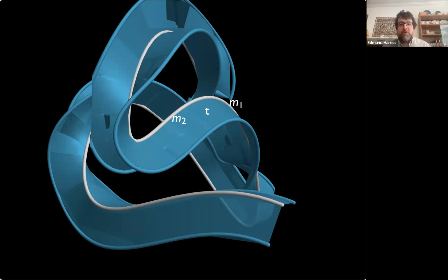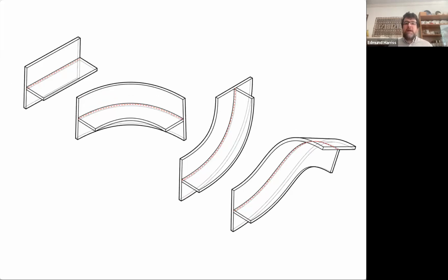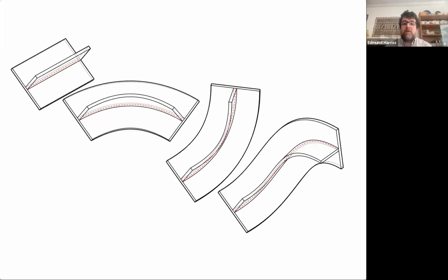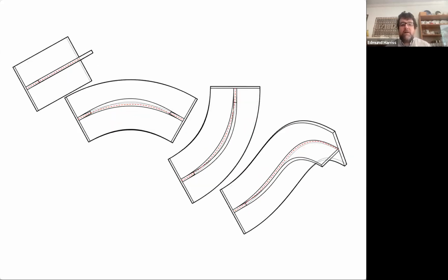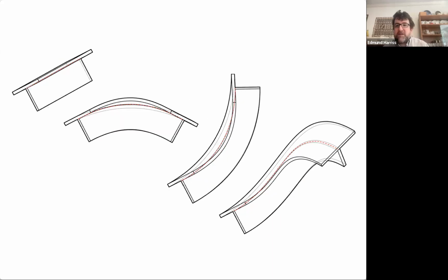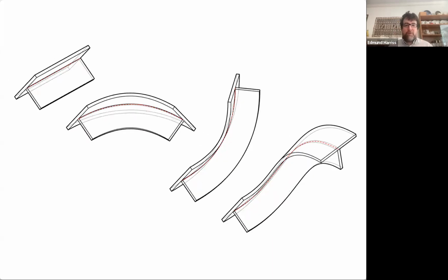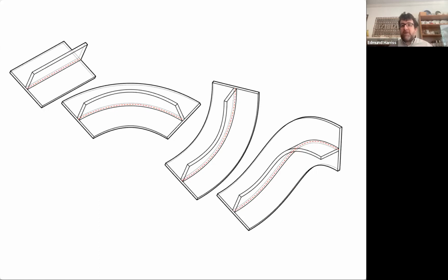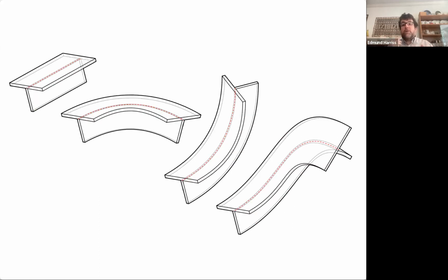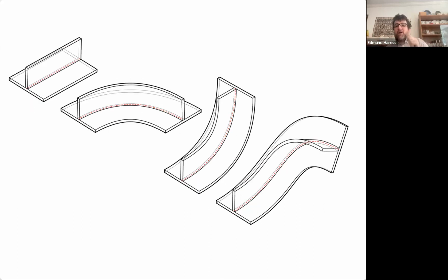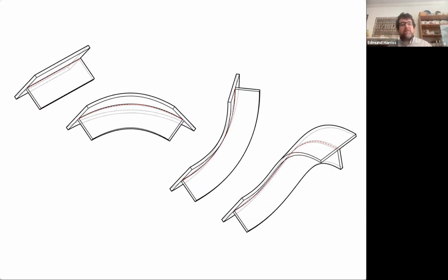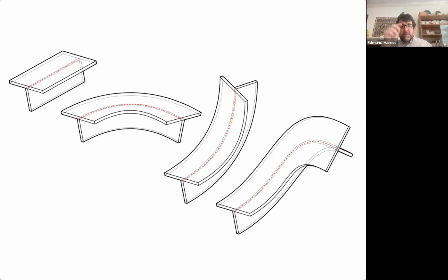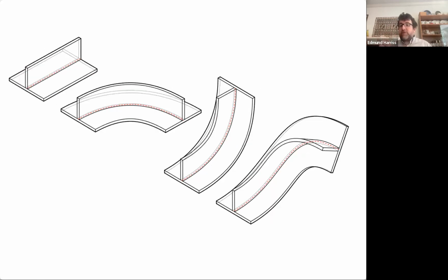They're called developable surfaces. And so now what we can do is take two of those flat cut pieces and attach them to each other to make a T shape. And basically what happens is that each shape can bend easily in one direction and is rigid in the other, but by putting them at 90 degrees, you swap the easy to bend and the hard to bend. And so if you look at these things, you have the surface, that broader thing, the top of the T, and then the spine, which is the shorter piece.